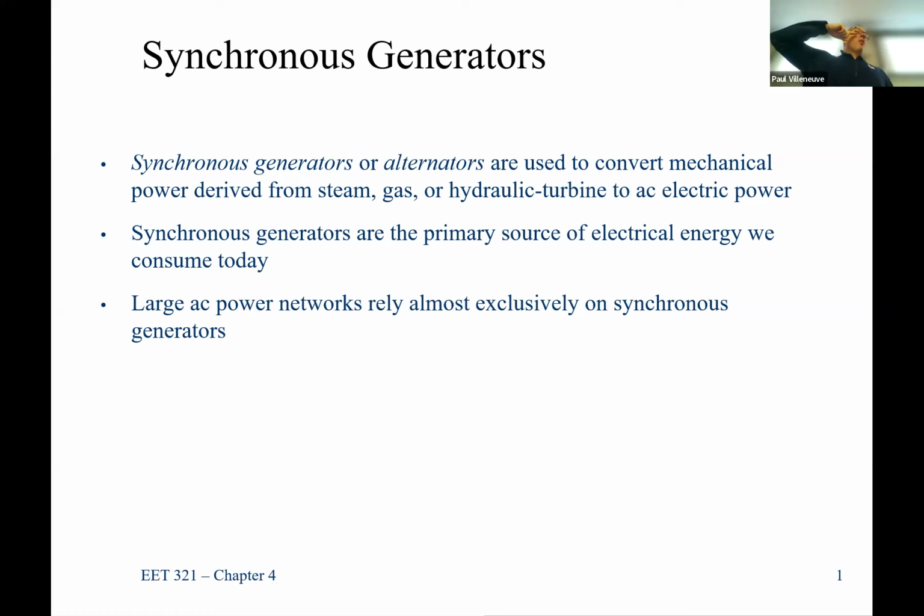The key thing about all AC machines is that the stator parts are always the same, regardless of whether it's an induction machine or a synchronous machine. They both have a three-phase set of windings distributed around the perimeter of the machine. The difference between a synchronous machine and an induction machine is what happens on the rotor circuit. You can actually swap the windings around, but for most applications, your rotor circuit is going to be the only difference.